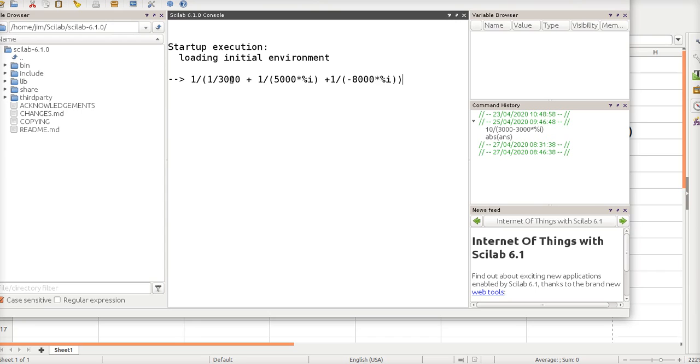So what I've done is put it in the parallel form, just like we would have done for a DC circuit, except now I'm using imaginary numbers, and I'm going to let Scilab do the hard work. And it tells me that I come up with 2855 and 642I. Now, without doing the currents, and then finding the total current by adding the vectors, and then coming back out to the impedance, I don't see how you can intuitively come up with this number.